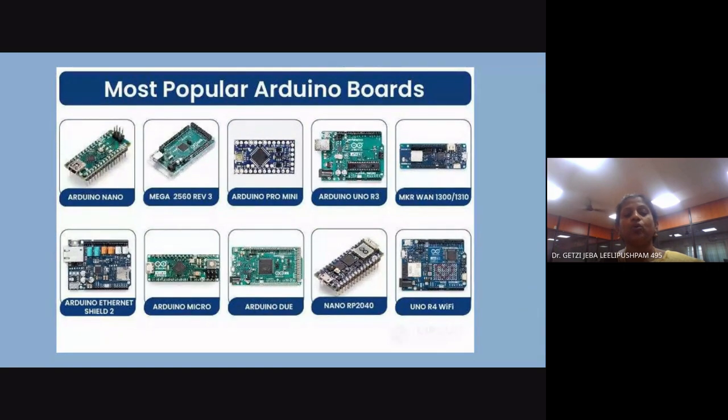Nowadays the Arduino has come up with more capabilities for programming. Usually the Arduino is programmed using the C-based coding structure, and the inbuilt functions are written in C and C++. But now even MicroPython is used for programming Arduino. All you have to do is upload a library, and then MicroPython can be used to code the Arduino.